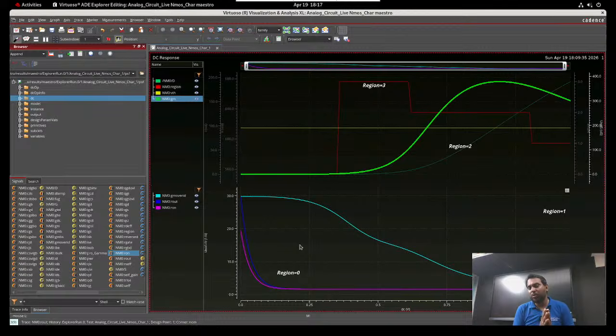Simply, you make a touch file, an empty file, with the command touch. You can use any library, any folder, any directory. In the directory you write the touch command, open the terminal, and write the name of anything, let's say xyz or abc, and the extension is important: .scs. If you write .scs, you are forcing that this file will be helpful for simulation.